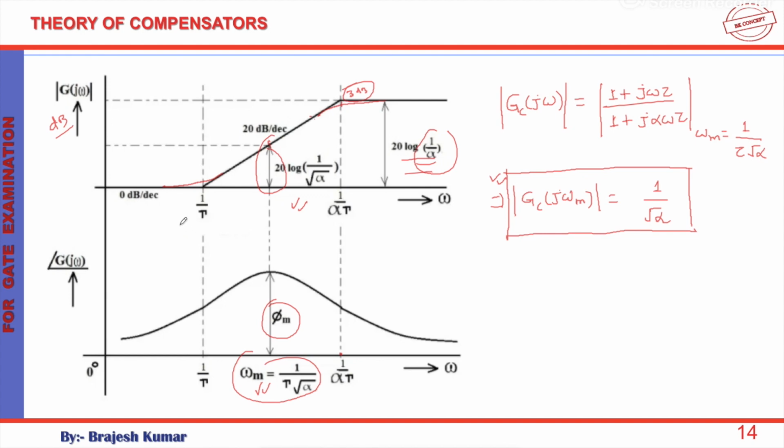So we can conclude that the nature of inherent noise in a control system is such that the noise signal frequencies are higher than the control signal frequencies. Noise is basically a higher frequency signal. So this Bode plot clearly represents that in the case of a lead network, the high frequency noise signals are amplified